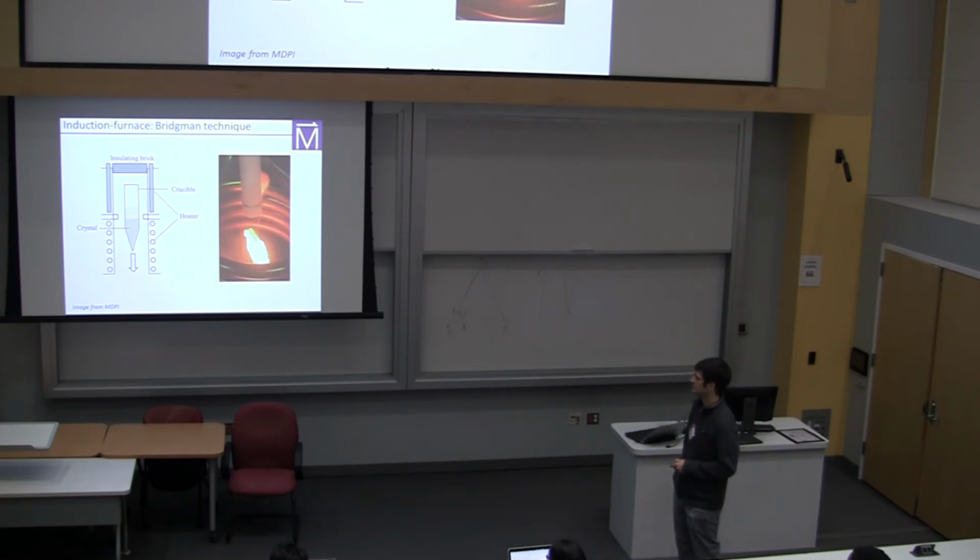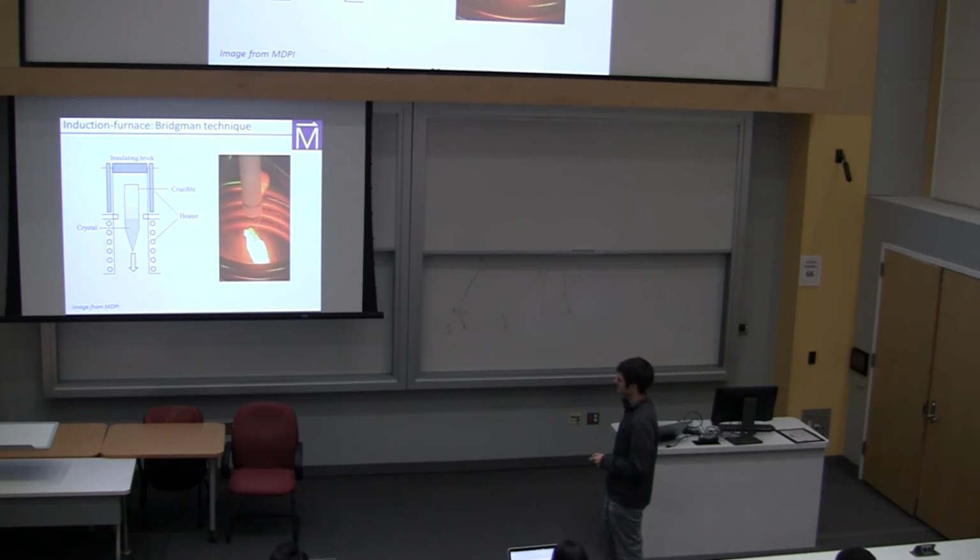So you can also use this setup for any sort of Bridgman growth that you might like to do. This is why we have a crystal puller on here in the first place. So the idea is that you may take a crucible and have a sharpened point on it, and then load this crucible with a polycrystal of whatever it is that you're trying to grow. You should bring it into the hot zone.